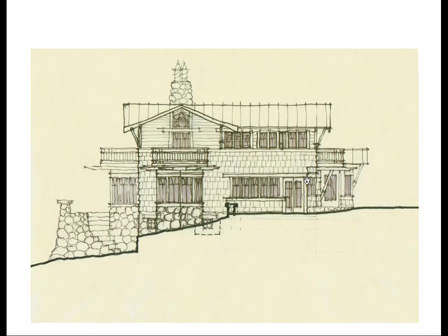In the sense of an elevation, you're not actually cutting through the building. You're doing a parallel, mirrored projection of the face of the building, but essentially you're only cutting through the earth, or whatever it is the building is sitting on. So in this elevation, you're cutting through the earth, but not through any part of the building. The only place where the thickest line is going to be is the cut of the earth. You can see that this marker line is by far the thickest of everything else in this drawing.